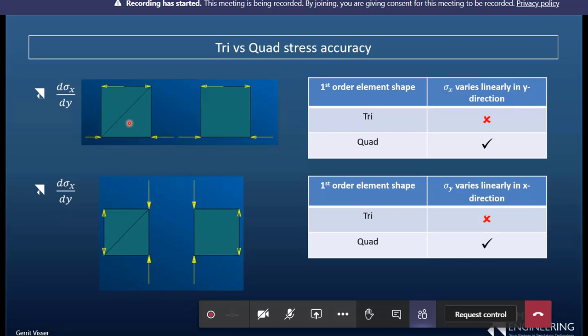Okay, now if you're a more advanced user, there's a lot more nuances to that, because you know at some point you need to mesh significantly finer, and what a good mesh looks like for a TET4 is different than it would be for a TET10 or a X8 or whatever kind of a model.